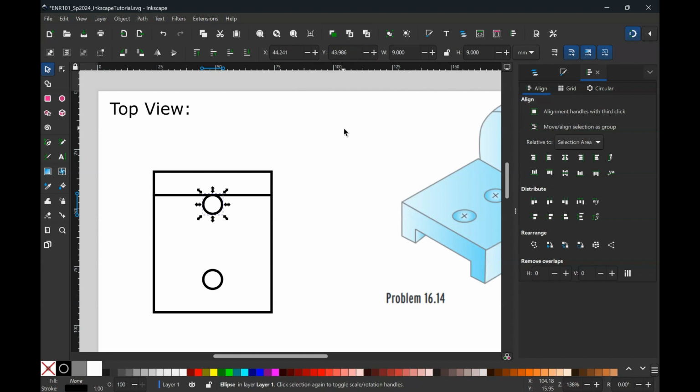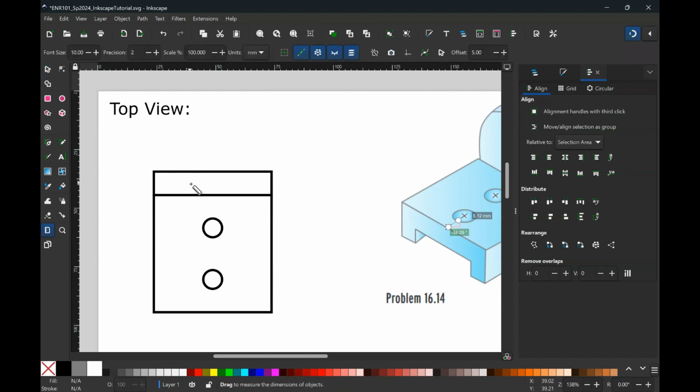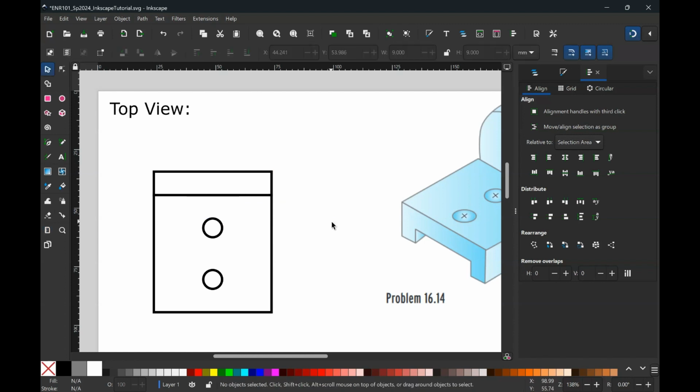And we can change the offset manually, giving us more precise control, exactly the distance between these two. You'll see that the amount that they shifted by from center to center is here about 10 millimeters distance. So one reason why we use these programs is it allows us to be very precise about the movements of each of these things, which is very, very helpful.